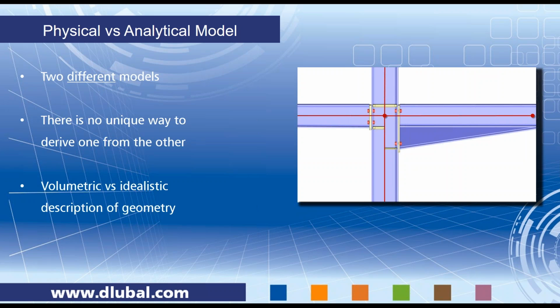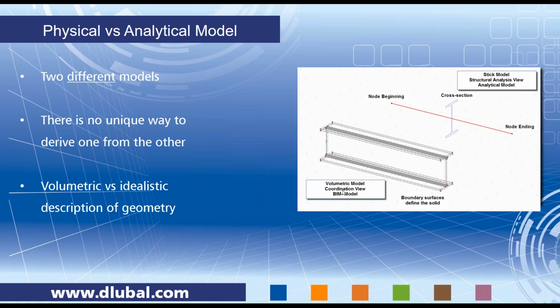And the second thing is typically when we have a CAD application or a BIM software, we have a volumetric view, and it means that boundary surfaces define a solid, and we get the real geometry of this structure, while in analytical software, we typically would describe this beam with a node of beginning, a node of ending, and a cross section that defines the stiffness and also the resistance of this structure.